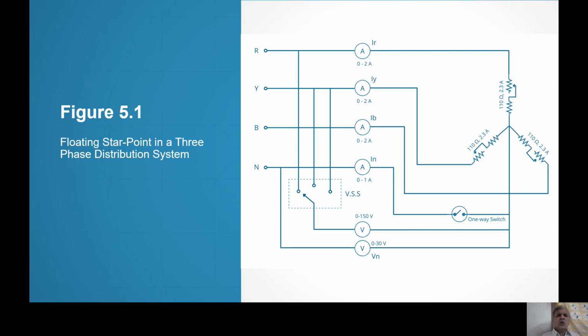It is not so that the load has to be kept unbalanced. Load is always unbalanced. And therefore, in the distribution system, load can never be balanced. In the transmission system, it can be balanced. At the generating point, it can be balanced. But at the distribution point, it is always unbalanced. And we want to see what is the effect of this unbalance.